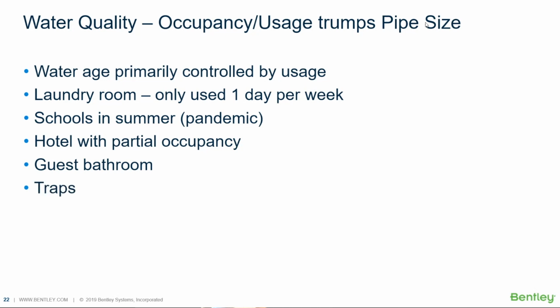The interesting situation I got involved in once was at a place where they were complaining about the odor in the restrooms, and it was the off season and no one was using the restrooms. And why did these restrooms stink? So what do you think caused that? Well, what I told them to do is go to every sink and just run the water for 20 seconds in the sink. And that solved the problem. Well, why did that happen?